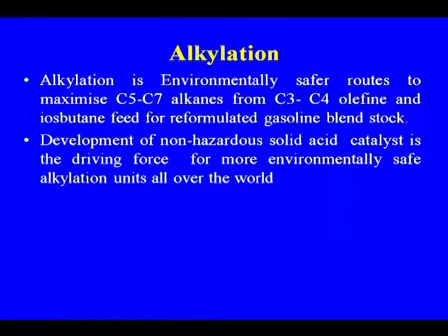So, why we are going for alkylation: it is an environmentally safer route to maximize C5-C7 alkanes from C3-C4 olefin and isobutane feed for reformulated gasoline blend stock. Development of the non-hazardous solid acid catalyst is the driving force for more environmentally safe alkylation units all over the world, and now slowly they are shifting to the solid acid catalyst alkylation process.